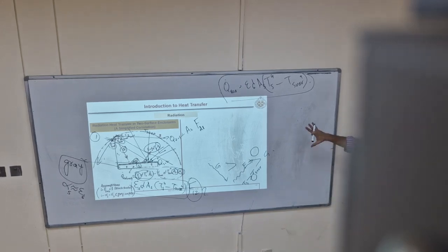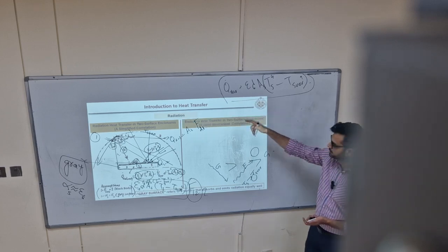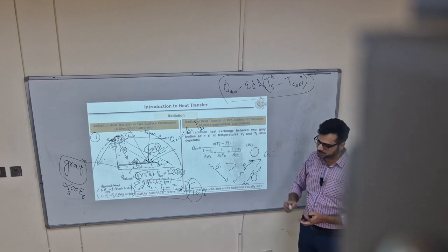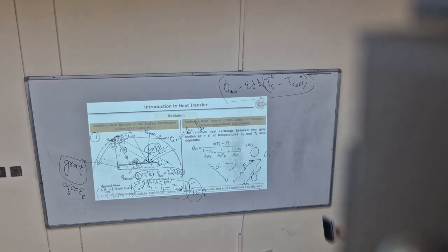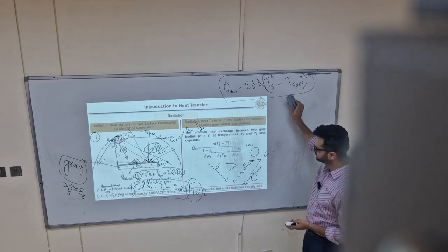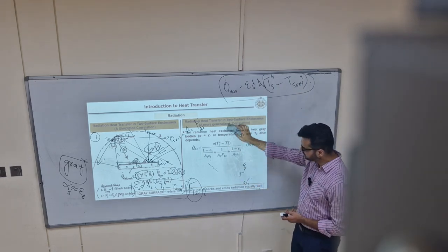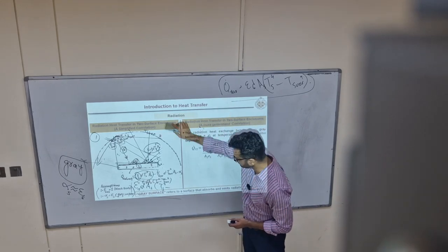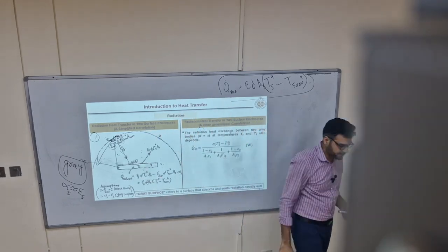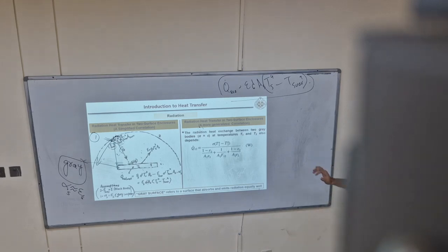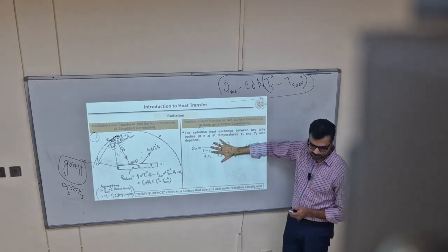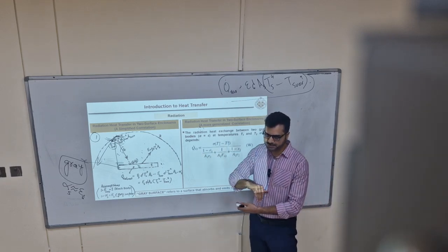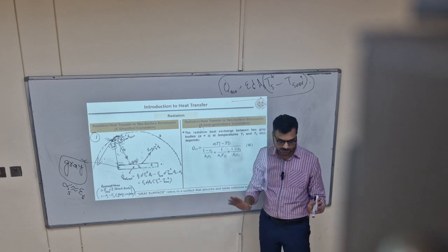So I have the derived form of that general equation in which these things are taken into account. This is this one. This is more accurate. This is from chapter 9 or 8 of radiation. I'm showing it in chapter 1 so that even if we are unable to cover it in the radiation part, at least you know that we have this more general form to find out radiation heat exchange between two bodies, one surrounding the other completely.